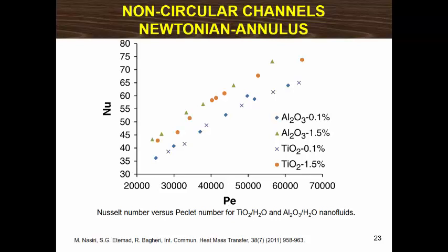On the other hand, the size of titanium nanoparticle is smaller than that of the alumina. Lower size of nanoparticle results in more mobility of particles and lower boundary layer thickness, and consequently higher heat transfer coefficient. Compromising between these two opposite effects causes almost the same value for the employed nanofluids when the nanoparticle concentrations are the same.